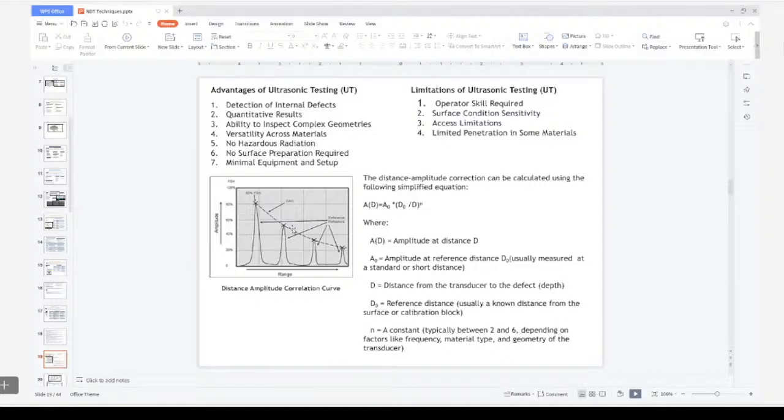Pores are a kind of volumetric defect, and it cannot detect them. When the ultrasound reaches the three-dimensional defects, it will go into the pores and get diffracted or scattered inside. The energy which has to come out and reach the probe will be minimal, which cannot be detected by the transducers. That is the only thing.